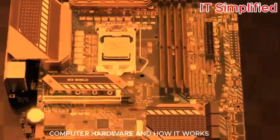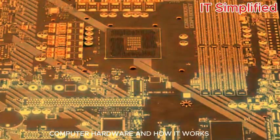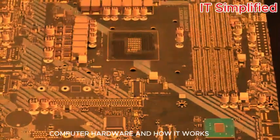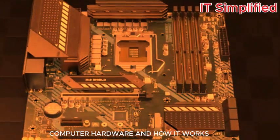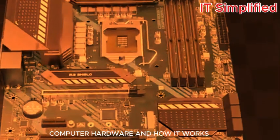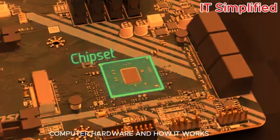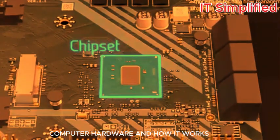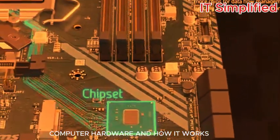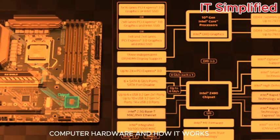This motherboard is a massive printed circuit board with thousands of wires running inside and a variety of microchips, components, sockets, ports, slots, headers, and connectors soldered to it. Perhaps the single most important and expensive component, aside from the bare PCB, is the chipset, which is this integrated circuit found underneath a heatsink down here and is connected directly to the system agent section in the CPU. Here's a diagram illustrating how the CPU and chipset are connected to everything else.